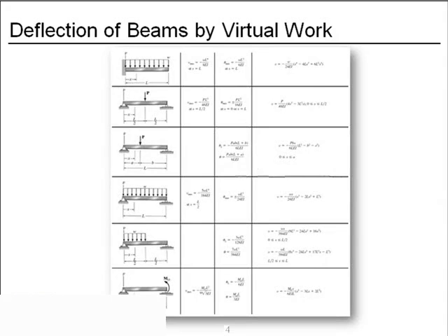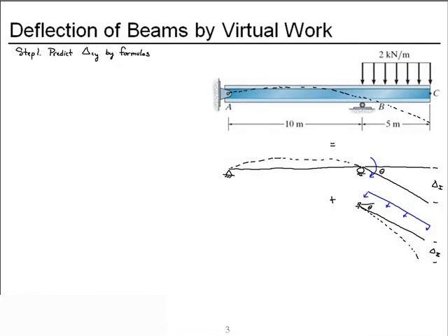So as we take a look inside the front cover, we have prediction for deflection for a cantilever uniformly loaded, and we have a simply supported member with a couple moment, and prediction of the slope or rotation at the end. The L refers to the left end, and so this quantity is the slope at the end where we apply the couple moment. Now if these formulas are too small to see, that's okay. Refer back to your textbook, but I'll write them down as we need them.